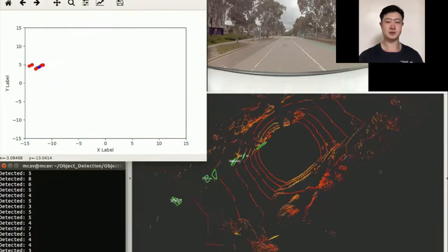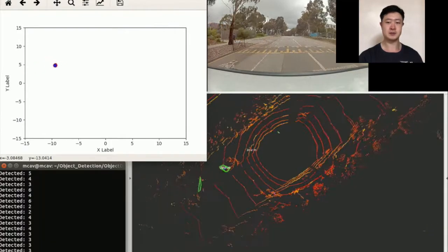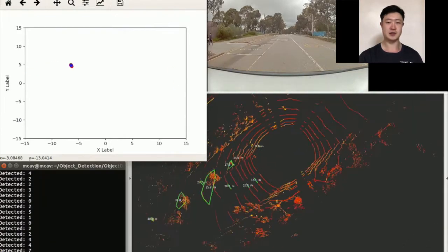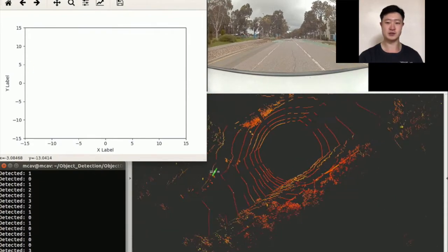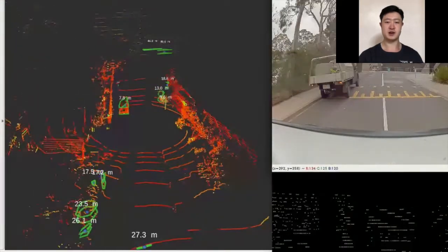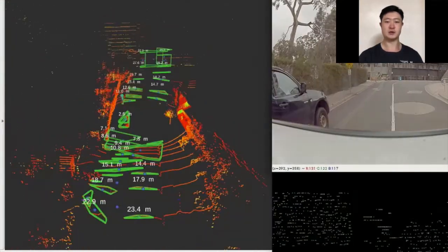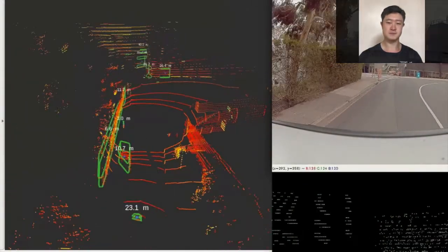The team is also aiming to classify and locate objects in 3 dimensions. Our plan is to take the 2D object detection information and match it with the 3D Euclidean clusters from the LiDAR. Currently, we're at the stage of rectifying the LiDAR point cloud in a way which allows us to find the 3D coordinates of the classified objects.